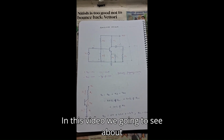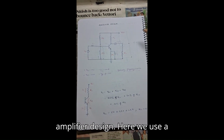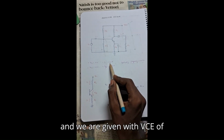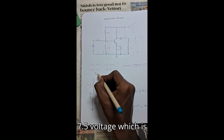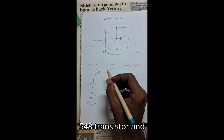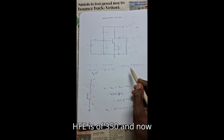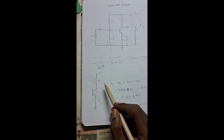In this video, we're going to see about amplifier design. Here we use a 15 V VCC, and we are given a VCE of 7.5 V, which is standard for the BC548 transistor, and an HFE of 350. And now we check the biasing.